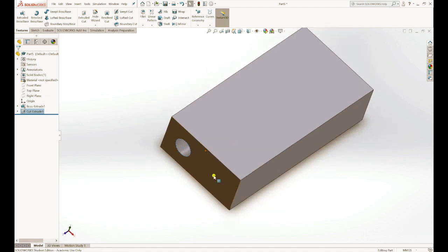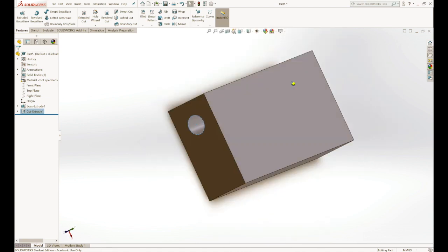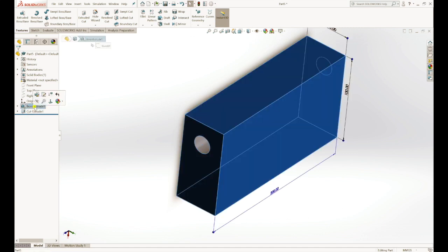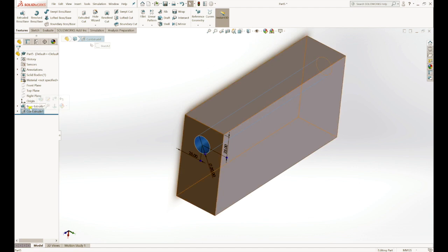There's a hole there. Well, as you can see, now we have made 2 features and 2 sketches. First we did a boss extrude, second a cut extrude. So if you click them, you'll see that they will be highlighted in your drawing. Like I told you in the beginning, this left side is where everything that you do is recorded.